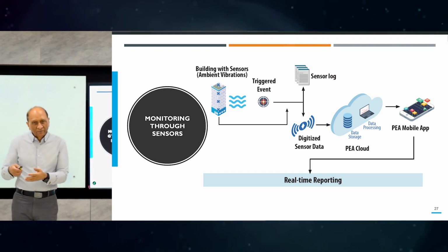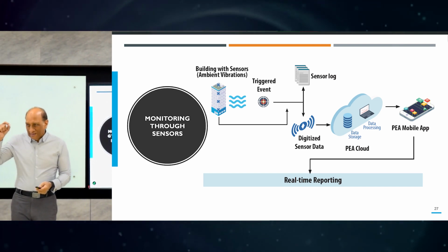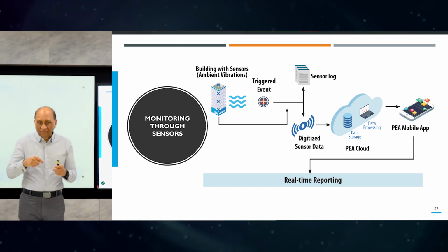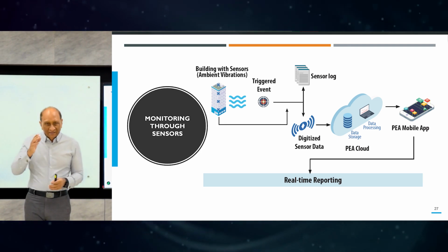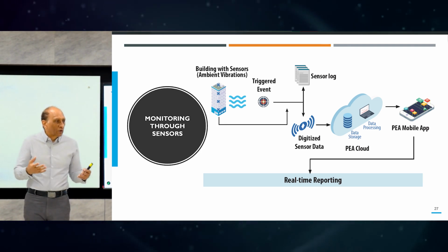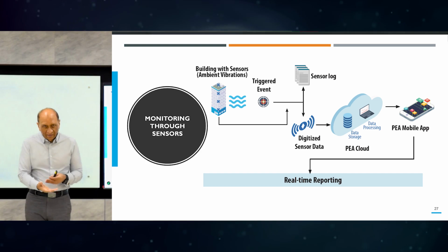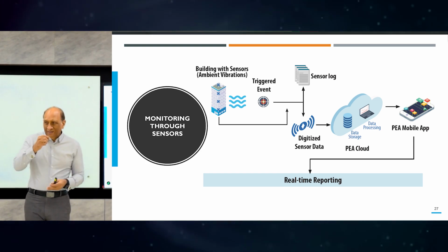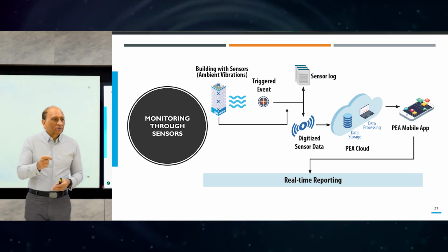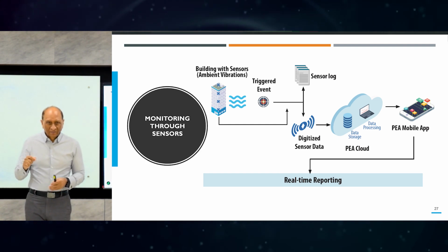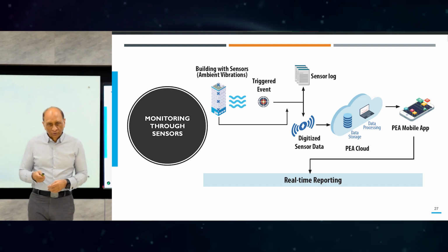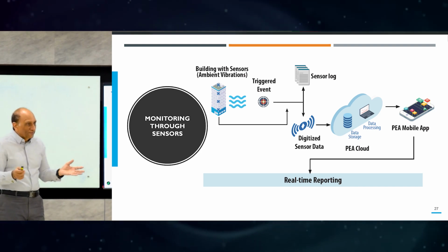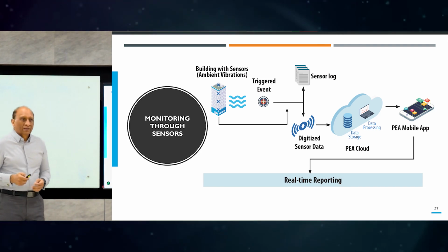So based on the response of the building, you can determine whether there's damage or not. No need to inspect. You will know from the analysis that certain things will be damaged or not because you have already got the model, you have a real ground motion, you have the whole thing, and you can predict whether this will cause any damage or not by sitting in the office. So that's the kind of thing that you could do if you have done all of that stuff that I mentioned to you. Okay.